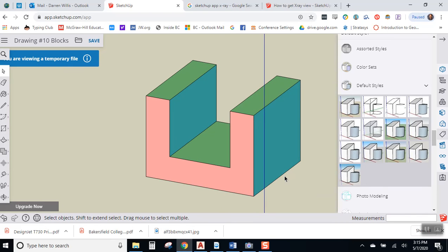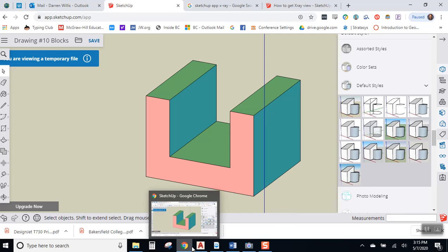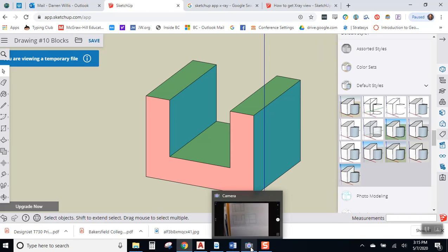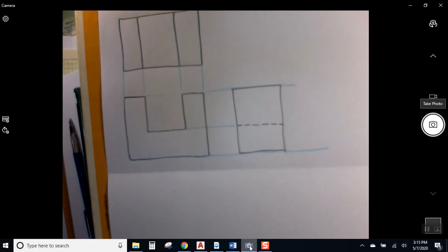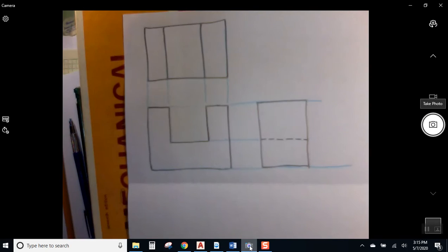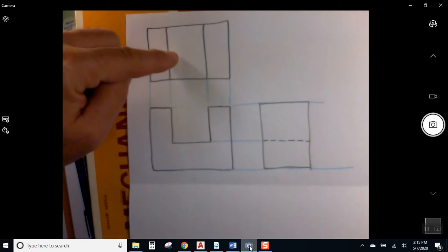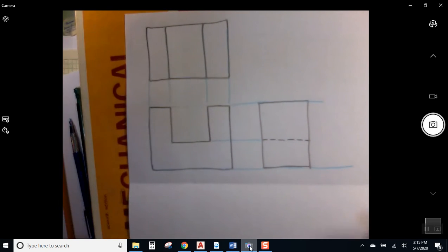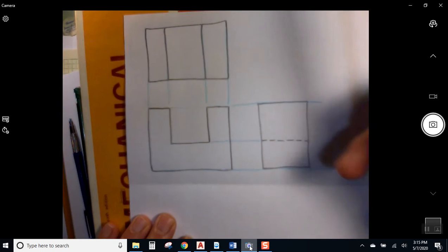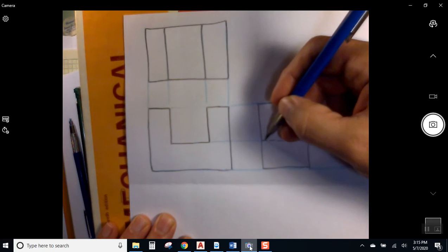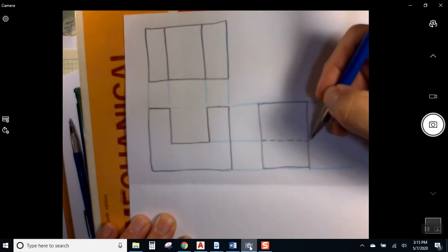Okay. Engineering drawing, remember, the deal is you have to represent everything you see at proper size and proper shape. Well, the hidden line allows you to do that. So I can draw the front, and I see the notch, and I look in the top, and I can see the notch. And now, with the side view, I also see this corner where that notch is, and I see it goes all the way through from the front to the back.